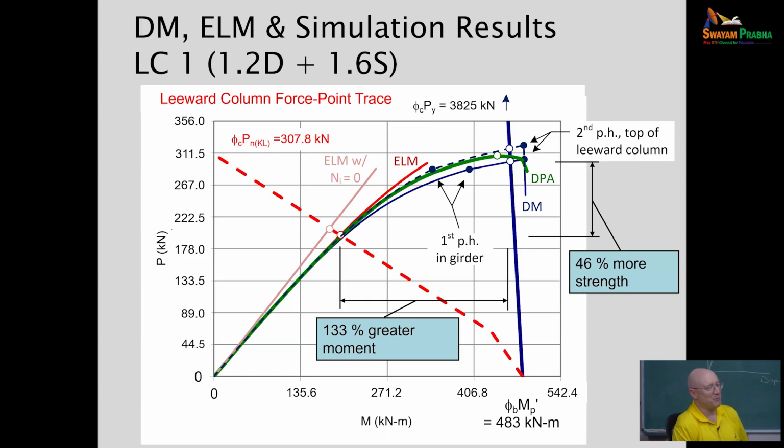So if we go to Appendix 1 of the AISC specification, Appendix 1 basically says, okay, everything we're doing with the direct analysis, here's how you do it with plastic hinges. And so Appendix 1 goes that next step to a second order inelastic analysis, and also says, if you want to do a plastic zone solution and use that for the design, here's how you do that. Distributed plasticity.